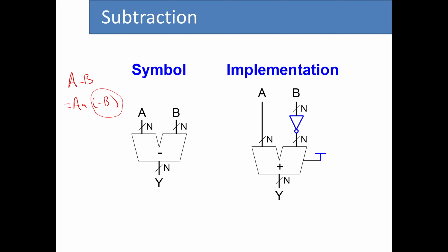So do you remember what the procedure was for calculating the 2's complement of a number? We basically had to invert all the bits and then add 1. That's exactly what a multi-bit adder can do for us, right? For inverting all the bits, we need to have some inverters in the path of the input B. So let's say if B is 32 bits, we basically have 32 inverters that are each inverting 1 bit in the value B. This is the flipping the bits part.